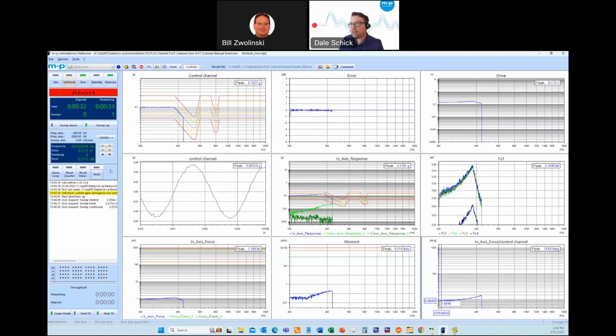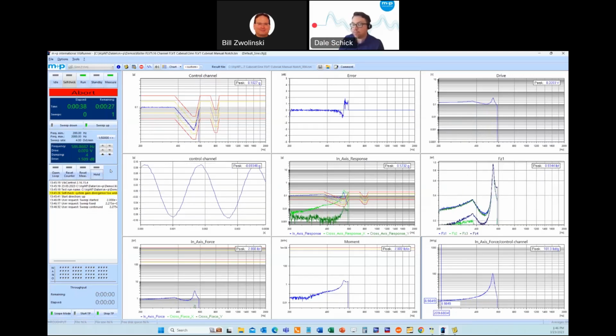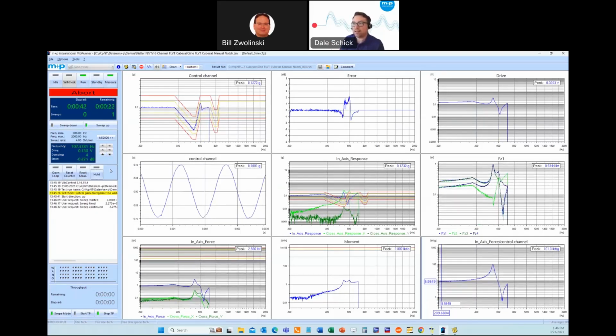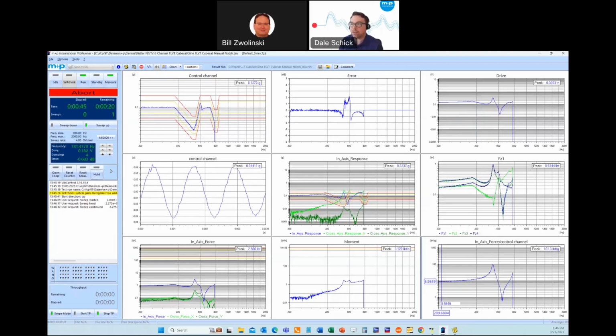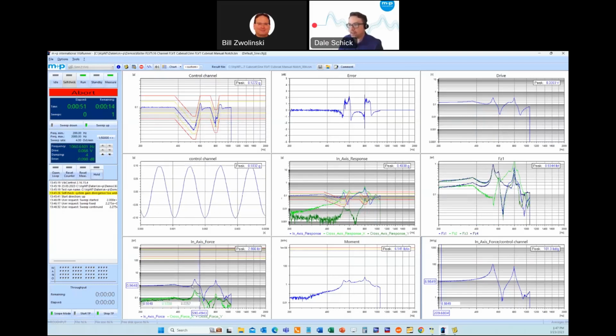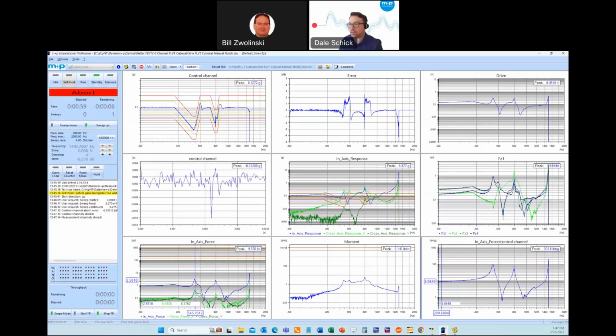So if you're doing an in-situ calibration on a spacecraft, you have to think about the accelerometer cables, the umbilical cables that are coming off of your test article. Any little tiny thing has to be added to this entire mass in order to provide the in-situ calibration. So we're going through our manual notch. We can see our in-axis force was limited, but only to about 2.5 pounds, which kind of overshot my target of 2. And a lot of this is because I didn't take into account the damping calculation.